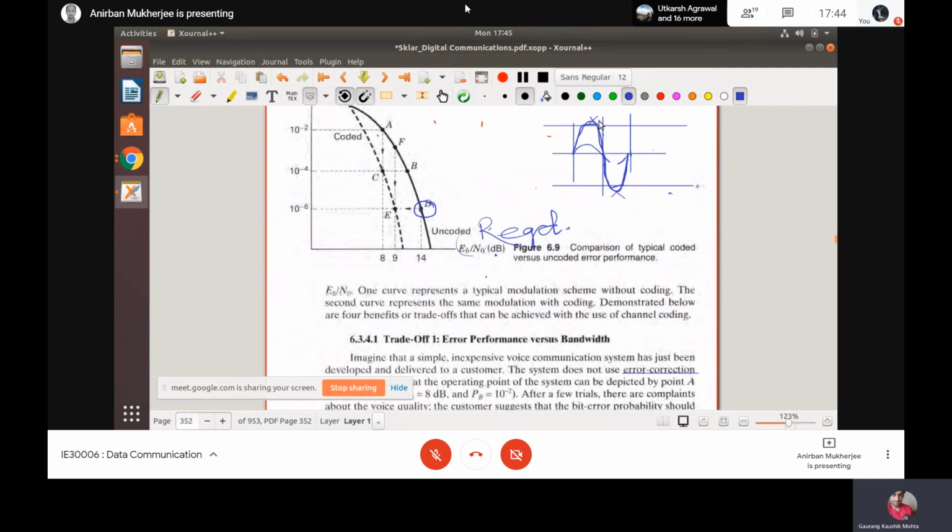Say in an op-amp circuit, you are familiar with the ideal op-amp. So when your supply voltage, the VCC and minus V, is 3.3 volt, you cannot go most probably beyond 3.2 volt or something. Okay. So if you are generating some sinusoid of say 3.5, or 3.4, you cannot generate it. So high power means always this type. So in your op-amp, say the supply is 3.3 volt, and say you have something like this, some output characteristics.